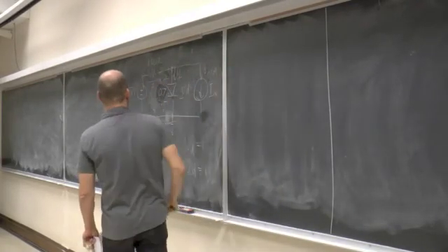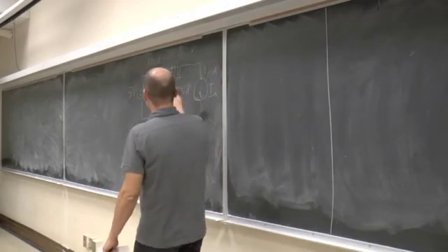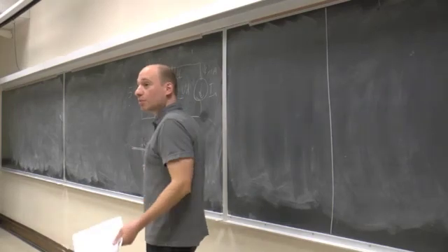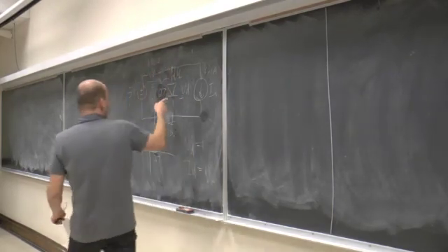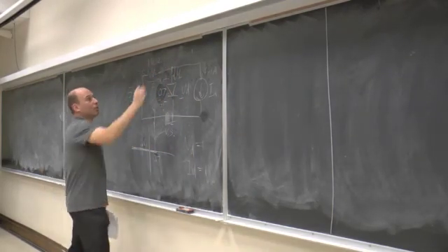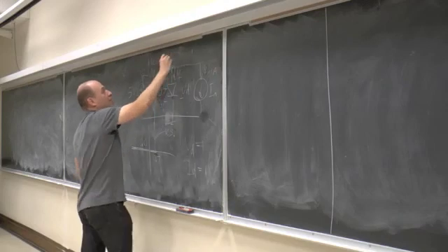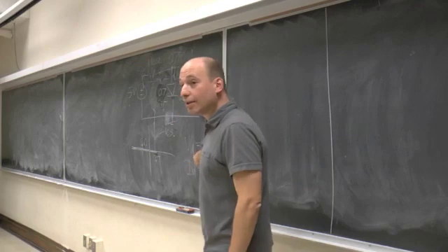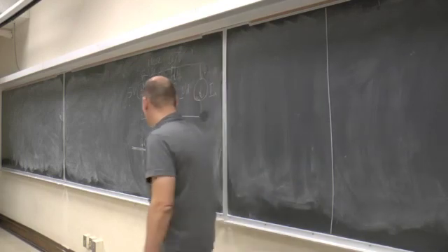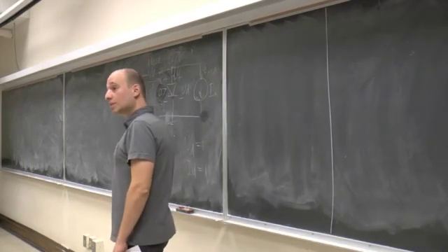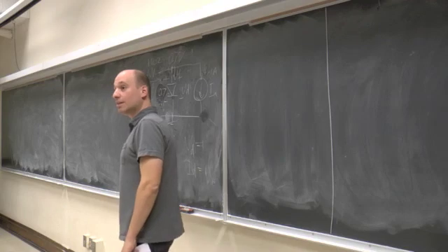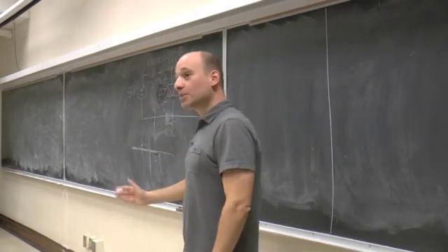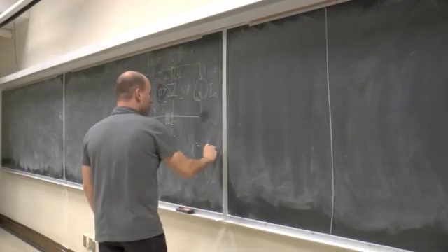But our assumption led us to turn on the diode. Therefore, the assumption was wrong. Therefore, the diode stays turned on, and we mark this as 0.7 volts. So the voltage across the diode, when the diode is turned on, is 0.7. This is the large signal model that you are studying. Independent of anything, it's turned on, it's 0.7. So that's 0.7 volts.